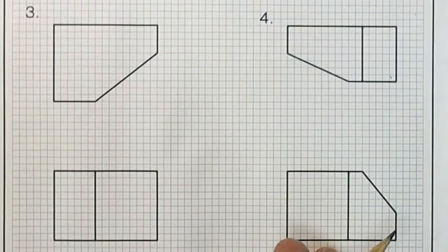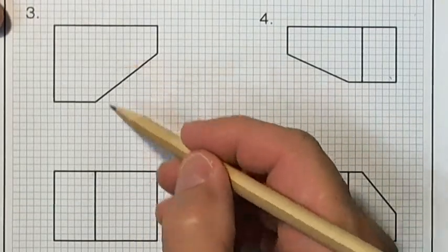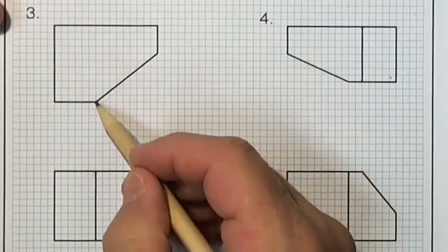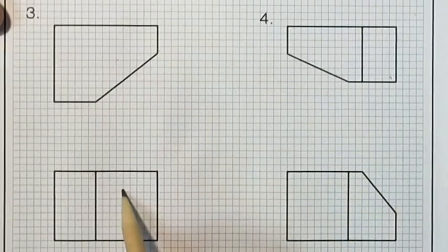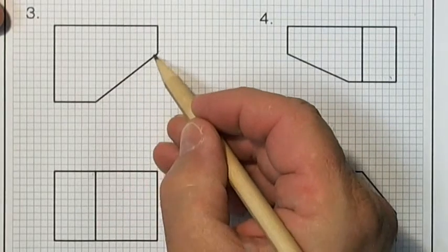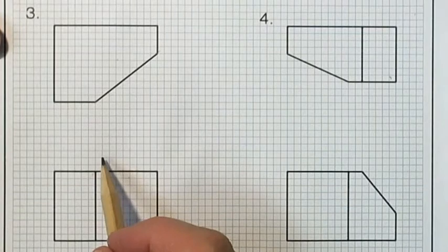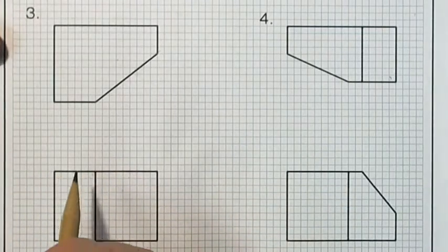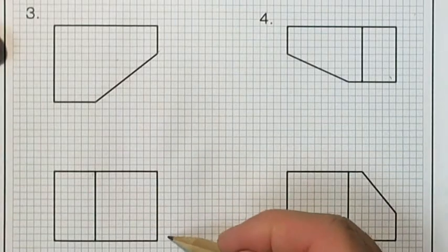Let's work one more on plate DIM1. Let's go to problem 3. Here I have a cut, and I can see the foreshortened surface in the front view. I can see it as an edge view in the top view. And referring back to dimensioning sheet 15, if I look at this, the front view is rather simple.